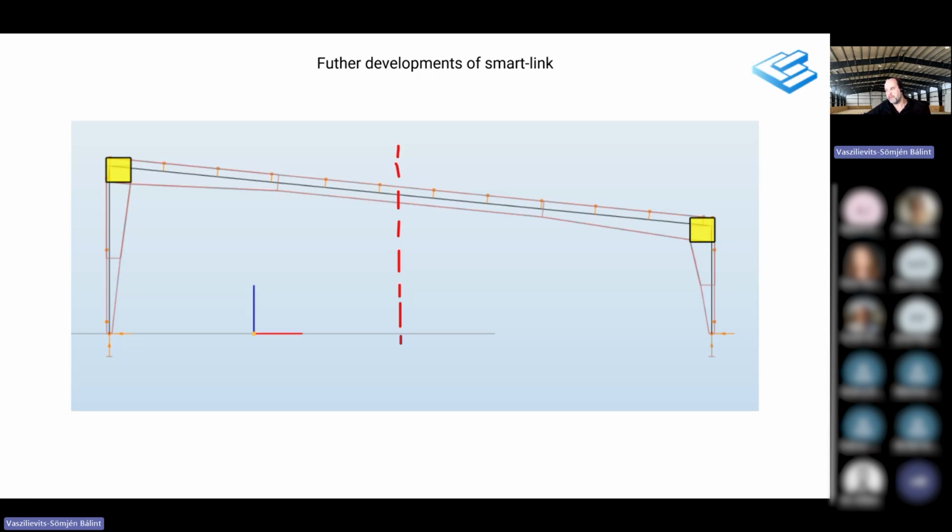But if we follow something very typical, that we have a bolted connection of the column, the pipe ends right below the rafter, and there is a bolted connection between the two there. In this case, let's assume a pinned connection, then actually the location of the pin is not here at the intersection of the red line with the reference line of the rafter, but exactly at the level of the bottom of my rafter.